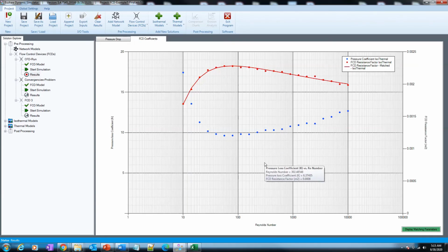But the important thing is here. This is the pressure loss coefficients, and we see it comes down and goes up like what you showed for the Baker Hughes select one. And so normally all of them have that sort of behavior. And this is what we need. So this is the resistance factor. And you see the software comes and curve fits this line over these. And you see these ups and downs happening because it's a simulation thing. But we need to curve fit it.